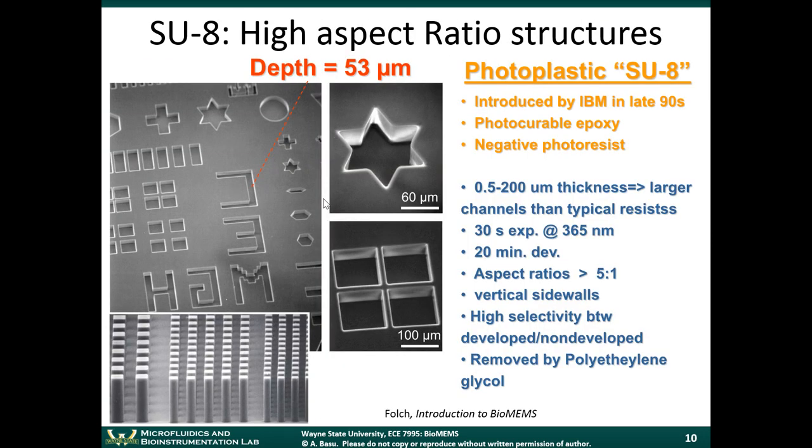these patterns that we're making on the photoresist are going to define microfluidic channels. Microfluidic channels have dimensions on the order of anywhere between 100 microns down to maybe 1 micron or so. Nanochannels have even smaller dimensions. But often, a lot of folks working in the microfluidics area want dimensions around 100 microns to 50 microns or so.